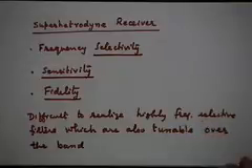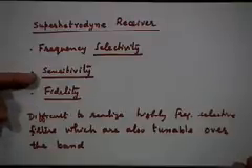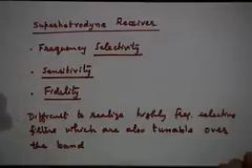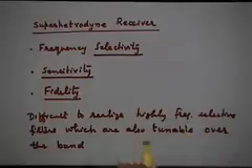Same thing here. Not only that, if you want good sensitivity, you should not just do a filtering operation. You should provide a large gain so that a weak signal is strengthened. Sensitivity means, how can you achieve sensitivity? By having a large gain in the receiver. So it should actually be an RF amplifier which is tunable, highly frequency selective, and provides you high gain.